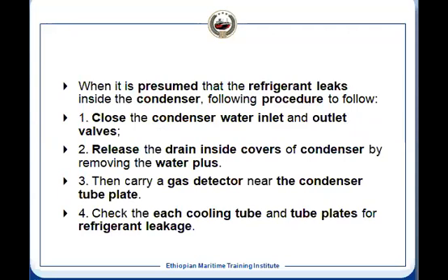Refrigerant leakage in the condenser can happen. Sometimes you check for leakage everywhere in the system and there is no leakage, but you keep on charging and keep on losing the refrigerant. It can be from the condenser. If it is from the condenser, it will leak because the refrigerant pressure is higher than the seawater pressure. It will leak to the seawater and go overboard, or it will go to the LTHT system. In the LTHT system, you will see bubbles in the expansion tank because the gas has to escape from somewhere.